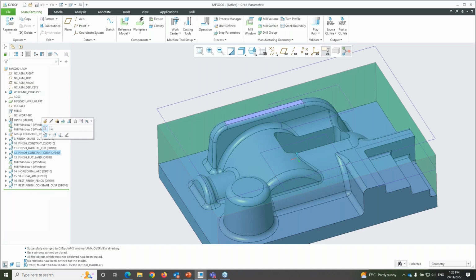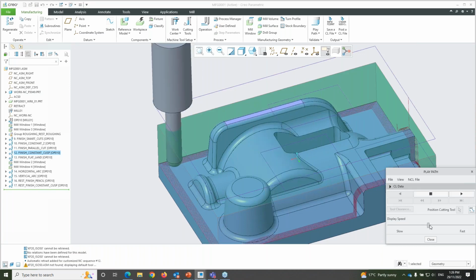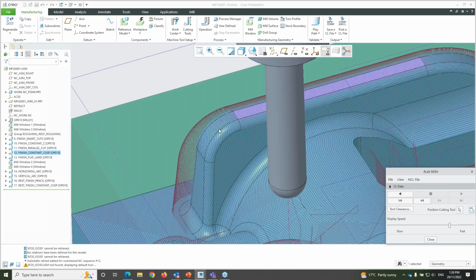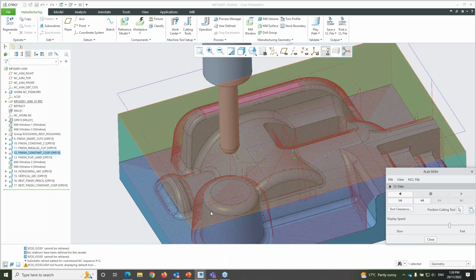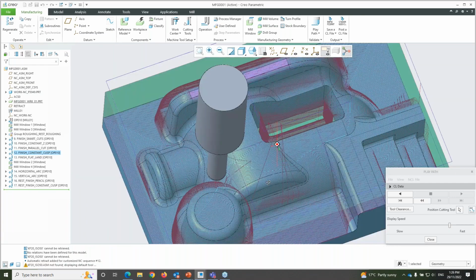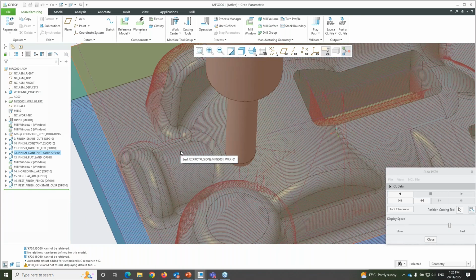This is a 3-axis pass, called constant cusp. I'd like to show you the finishing toolpath that is created inside high-speed milling. People from a manufacturing background can see what a beautiful toolpath is being generated. You can change the scallop height to make it finish and avoid any chances of polishing and things like that.